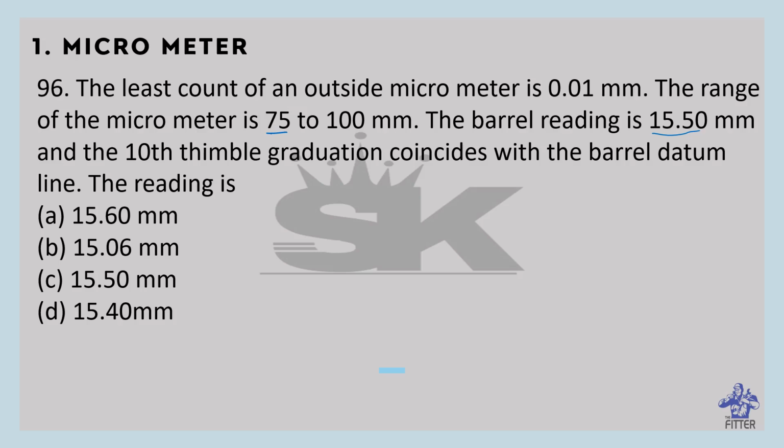The reading here, using least count: reading on thimble equals 10 into 0.01, that is the least count. So the answer is 0.1 mm.